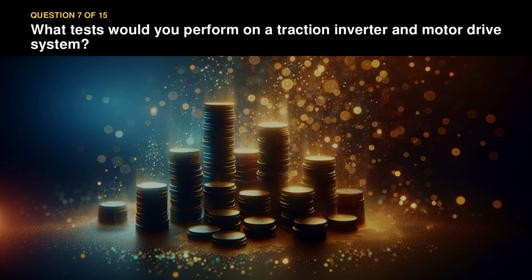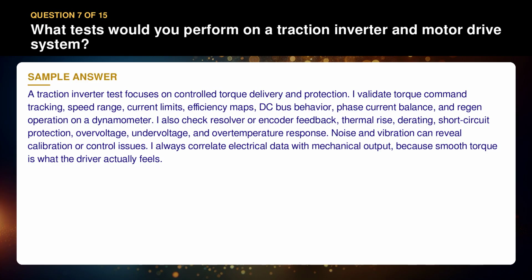Question 7. What tests would you perform on a traction inverter and motor drive system? A traction inverter test focuses on controlled torque delivery and protection. I validate torque command tracking, speed range, current limits, efficiency maps, DC bus behavior, phase current balance, and regen operation